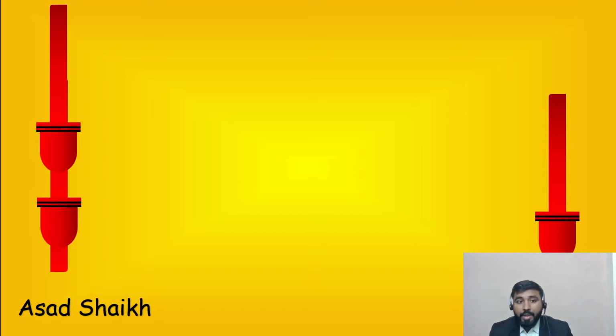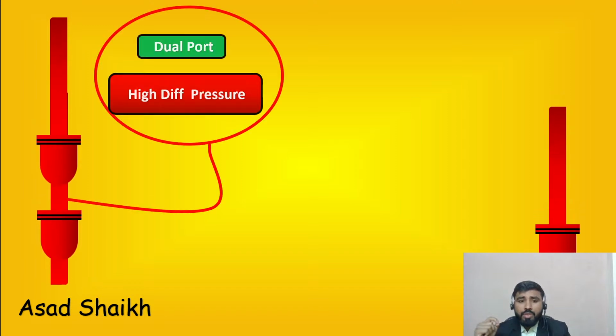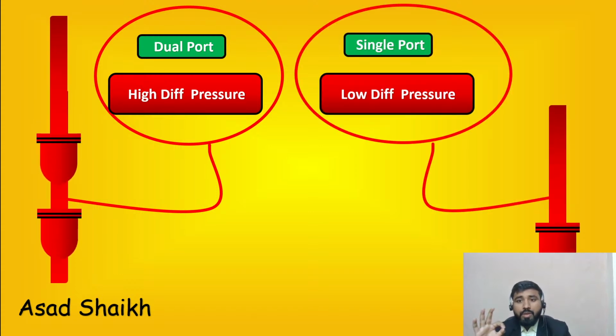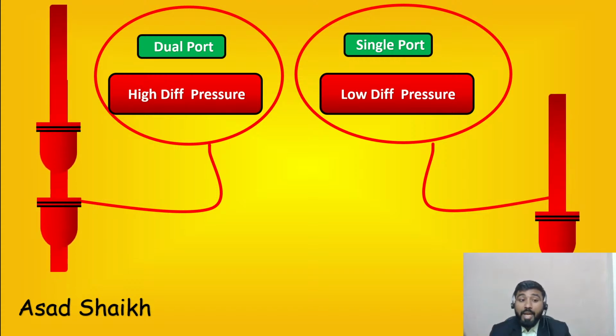Okay. So with dual ported design, as some of you said, there is going to be an issue. But overall, remember one thing: when it comes to dual port and single port, valve plug guided is good for low differential pressure applications. Dual port is good for high differential pressure applications. Okay, now let's look into answering the question of why it is not used in most of the applications.